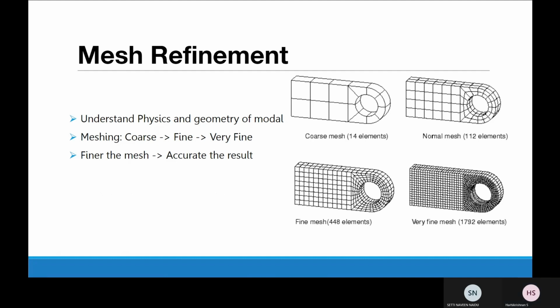Mesh refinement is the process of resolving the model with successive finer and finer meshes, comparing the results between these different meshes. This comparison can be done by analyzing the fields at one or more points in the model, or by evaluating the integral of a field over some domains or boundaries.